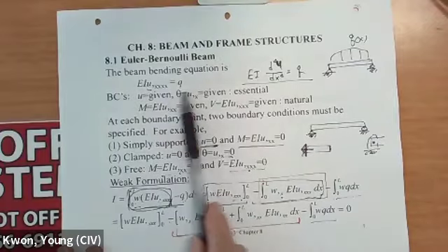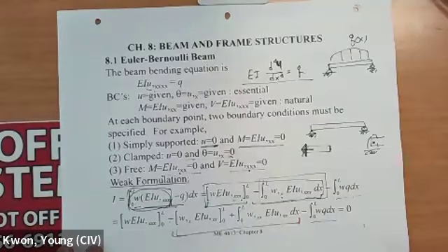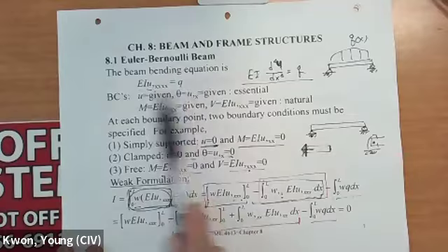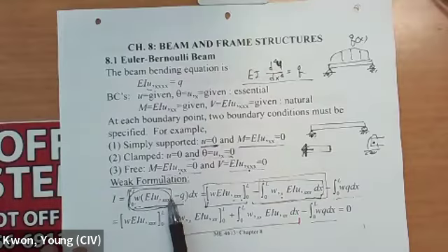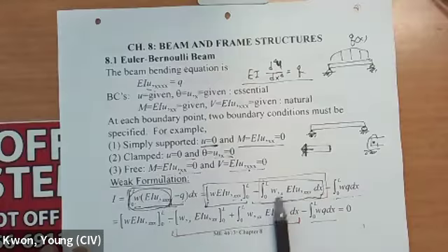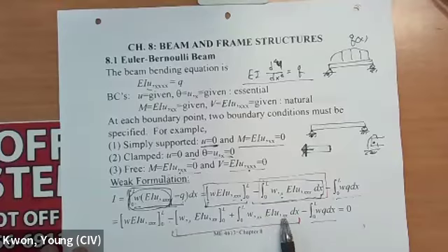Now, in terms of the finite element formulation, again we use the method of weighted residuals, just the standard procedure. Then you can see that the test function and the trial function require different orders of derivative. So we apply the weak formulation to weaken the requirement, as in Galerkin's technique. We apply integration by parts, and still have a first order derivative and a third order derivative. Applying integration by parts one more time, you finally get second order derivatives of both the test and trial functions. So we stop there.